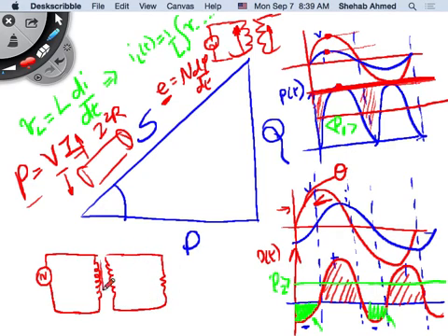Right, so this is a nicer transformer. If I don't have a load here, then the current that will flow will depend on the impedance. We said, right, if this is the voltage at the input, this is a back EMF that was created. We agree that in the transformer drawing that I had, I didn't even have a second winding. The one where I drew the core, you don't have to have a second winding for that back EMF voltage to develop. You don't need to.